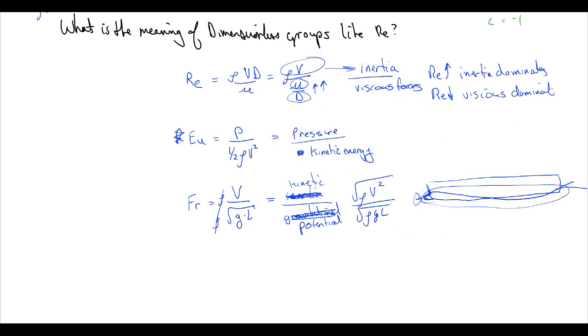And so we fundamentally want to increase the length of container ships in order to get them to be more efficient and go at higher velocities. Although you'll notice that it's the square root of L over V. So if we were to plot the maximum velocity of a container ship versus the length, if this is our V and this is our L, we're going to find out that we get something like this, right? So you get diminishing returns the larger and longer your ship gets. So in order to double your velocity, you have to go 4 times your ship length.